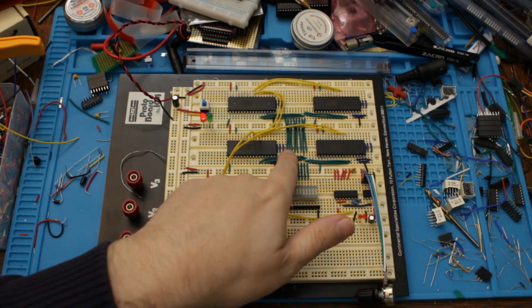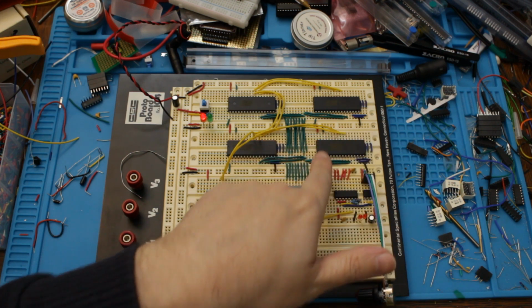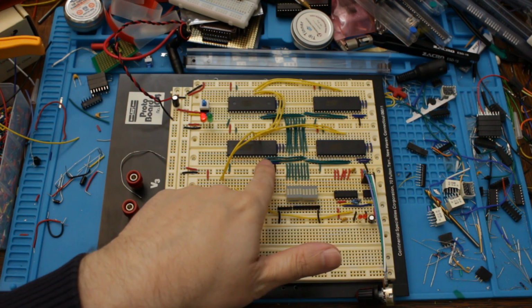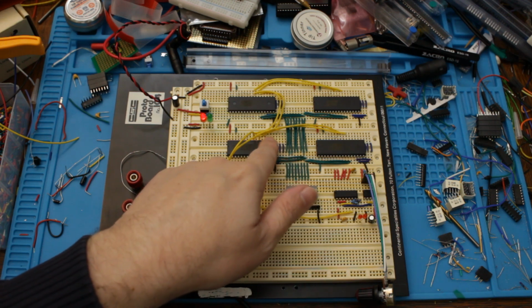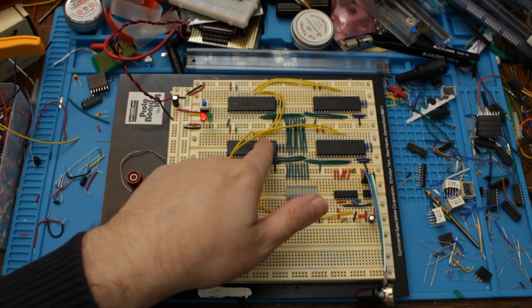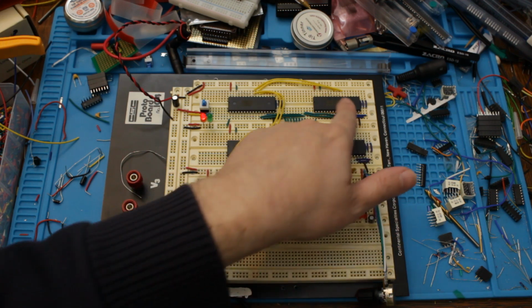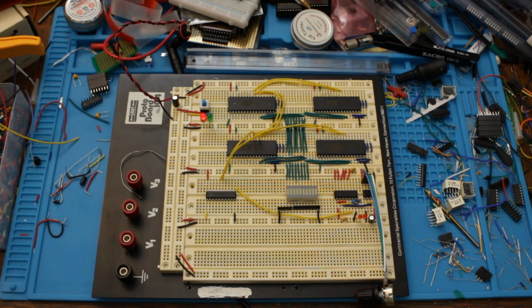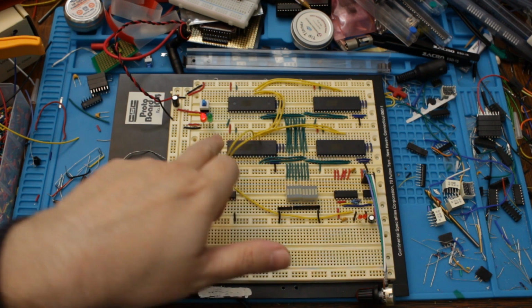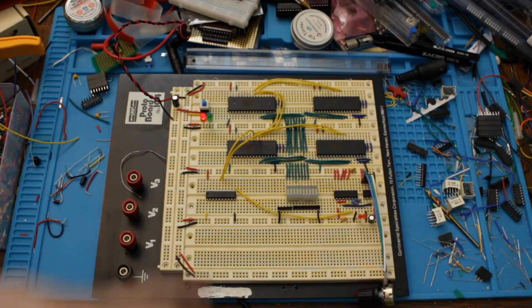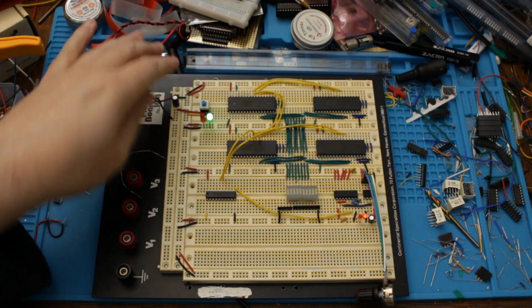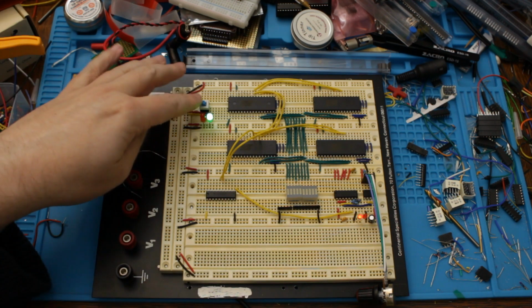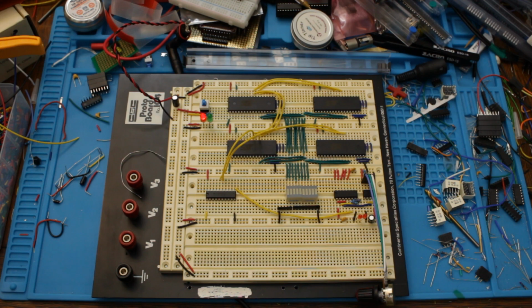And I've used blue for the data bus, but you can't see very much of that on here. Basically all I'm doing is routing the bottom 3 data bus pins around the side of each EEPROM so that I have a nice block of 8 pins of data bus along the top right of each EEPROM. And I'll wire those through to the ARM CPU using long ribbon cables. What else is there here? The write enables are all tied high. Oh, and I also set up a sort of on-off switch thing over here, so you can see the clock obviously responds when I turn it on, and the lights indicate whether it's on or off.